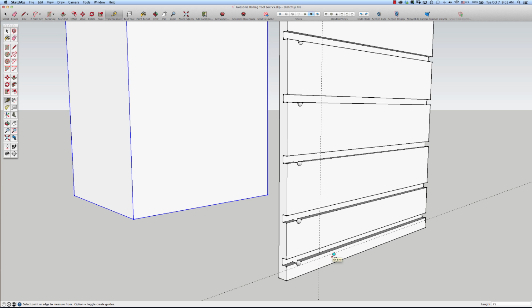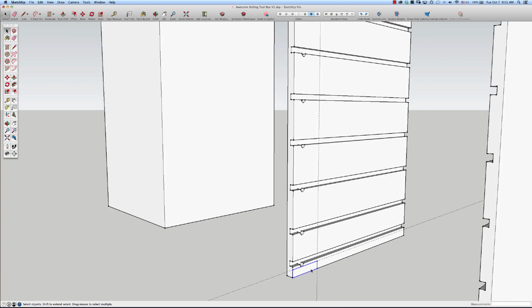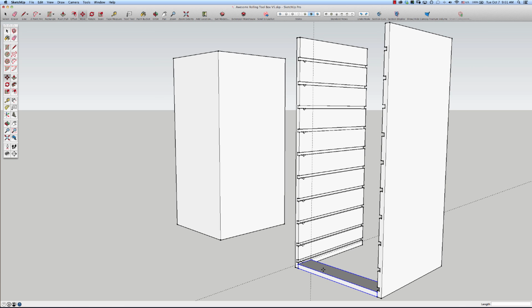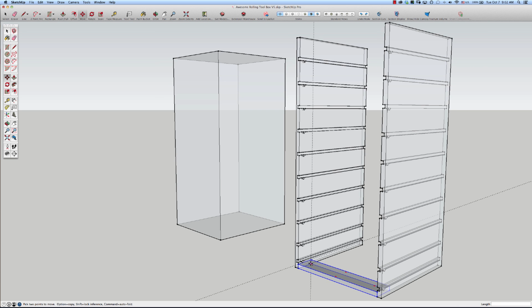And then I'm going to hit the R key for rectangle. Just click down there to there, and then double click, right click, make group. And then all I need to do is get back into that group, click on the surface, P key for push pull, come and just touch anywhere on this edge, move, copy. I'm going to grab this lower corner and I'm just going to move it back. I've got shift held down, it locks into place.